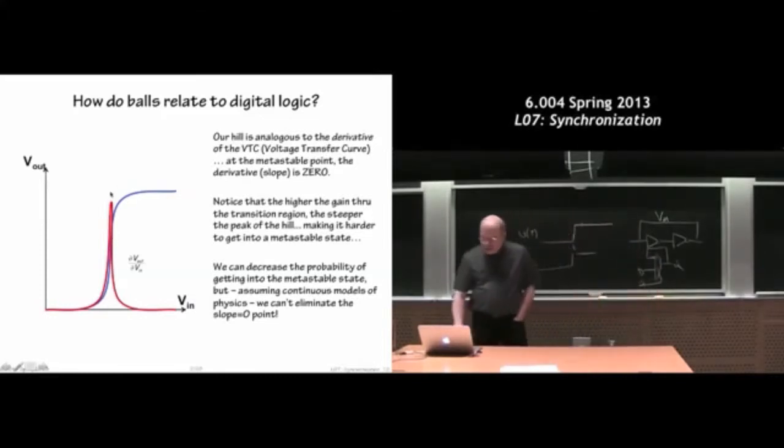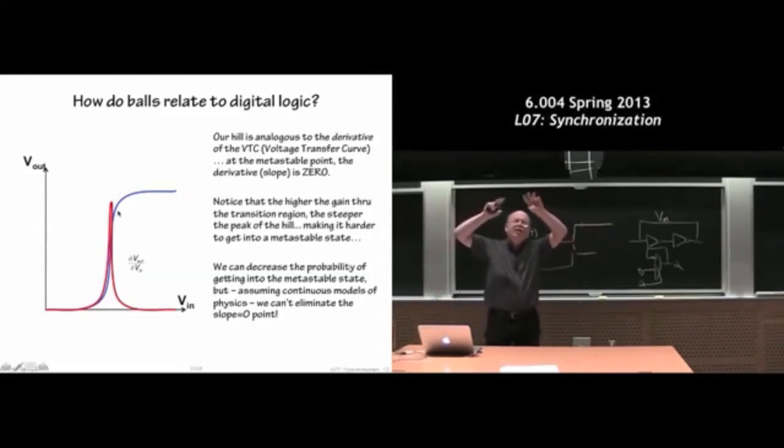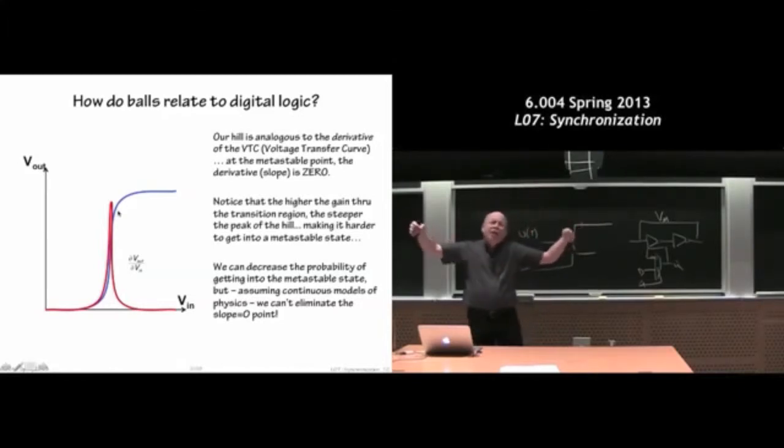But it is possible to end up at a point where you can put the voltage at where the gain of the system is in fact zero. In other words, nothing's going to happen to this output voltage. This voltage is sort of stable until you get to either the voltage just on one side or the other, and now we have either positive gain or negative gain, and now the amplification provided by the electronics will produce an output voltage which will go back to one of the bistable states. But there is this magic middle point.